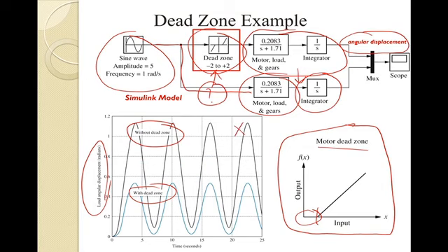But then you get into the lab, and physically, if you have that dead zone or that backlash or something else, you would see the response shown in blue, and you'd be like, wait a minute, that's supposed to go to 1.1, 1.15, but it's only going up to like 0.5 here. There's a big difference in what I'm seeing and what's wrong. It's usually that something wasn't modeled appropriately or correctly. Not always, but that could be the culprit that you can run into.